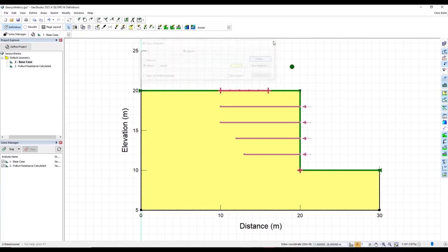According to active earth pressure theory, this excavation would not stand. The factor of safety would be exactly 1.0, and the critical slip surface would be inclined at 45 degrees plus the friction angle divided by 2, which in this case is approximately 60 degrees. We're adding these 4 layers of geosynthetic to stabilize this slope and increase the factor of safety.